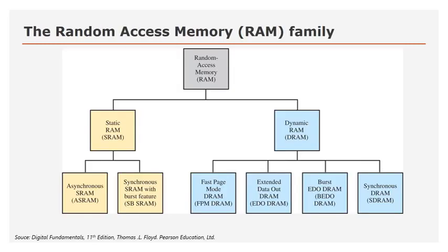Okay, so let's look at this RAM family. I don't want to go into too much depth here. I am just quickly going to tell you about an SRAM and a DRAM, S for static and D for dynamic RAM. Just the quick differences between the two, and that's all I want you to know. So if we look at the static RAM or SRAM, basically what happens here is that your data is stored in a latch, and in other words, the data can stay there inside this RAM indefinitely as long as DC is applied, as a DC source.